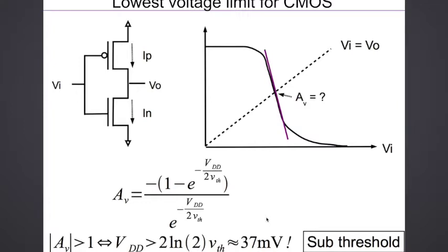But with the advent of wearables and ultra low power devices, it became very interesting to go back and look at this question: how low can I go in my supply voltage? In the early 1990s, a lot of activity started to experimentally get to this number. There were people in laboratories who could demonstrate circuits operating down to 100 millivolts, and some laboratory demonstrations show circuits operating at even less than 100 millivolts, about 80, 90 millivolts and so on. So this is also borne out from experimental considerations.